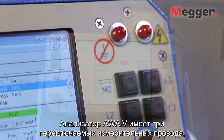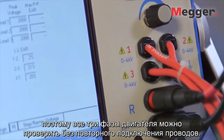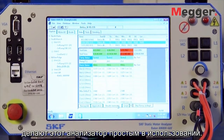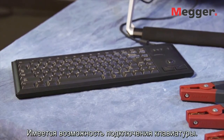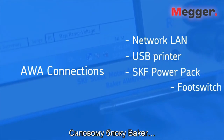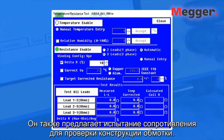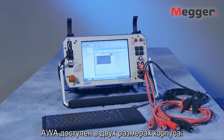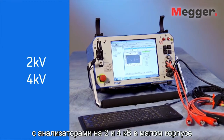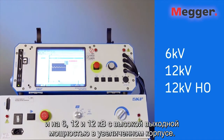The AWA has 3 switch test leads, so all 3 phases of the motor can be tested without reconnecting the leads. A color touchscreen interface and familiar Windows operating system make this tester easy to use. A keyboard is available as well. The AWA can also connect to a network LAN, USB printer, power pack, foot switch, and safety lights. It also includes a resistance test for winding construction tests. The AWA is available in 2 package sizes, with 2 kV and 4 kV analyzers in the small package, and 6 kV, 12 kV, and 12 kV high output in the large package.